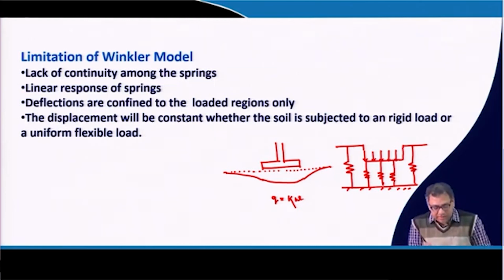So, as mentioned, deflection is confined within the loaded region, and another limitation is we know that for flexible footing and rigid footing, the deformation patterns are not the same, because for the rigid footing your deformation is more or less uniform. Okay, and for the flexible footing, as I have drawn, at the center the deformation will be more, and at the edge the deformation will be less.